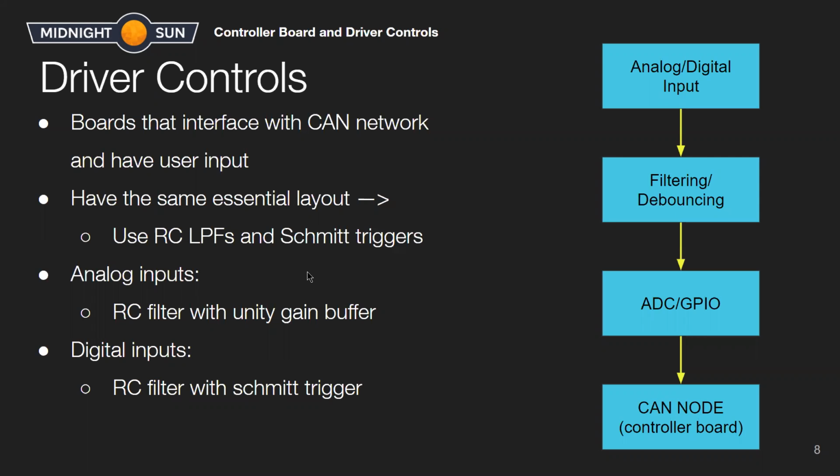They're all boards that are CAN network nodes, as well as interface with the user somehow, or gain some sort of user input. And so this diagram on the right is essentially how every single driver controls board works. And by the way, the driver controls boards split up into steering interface, pedal interface, and center console.